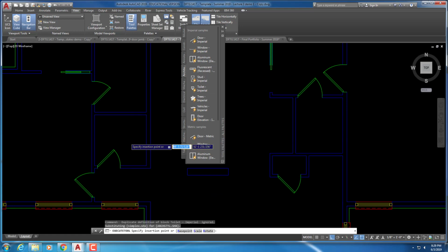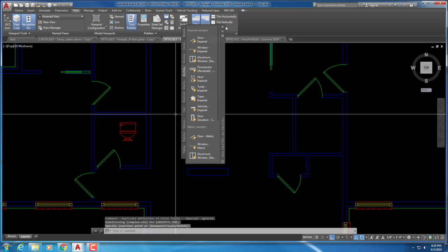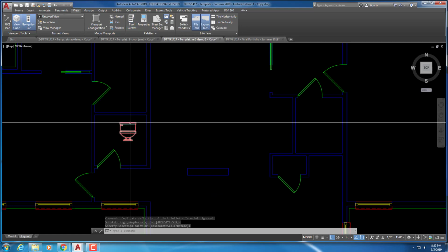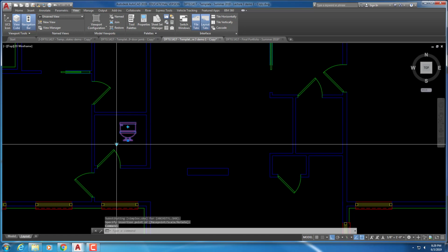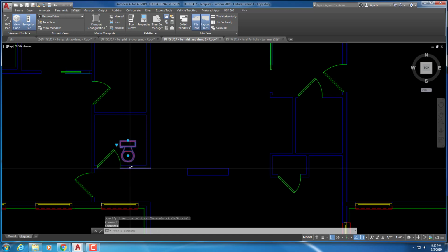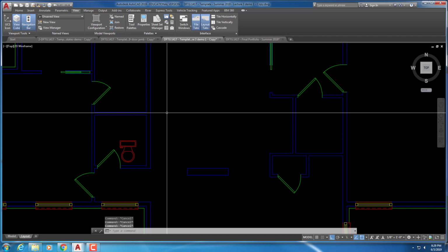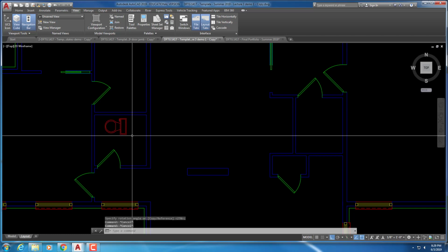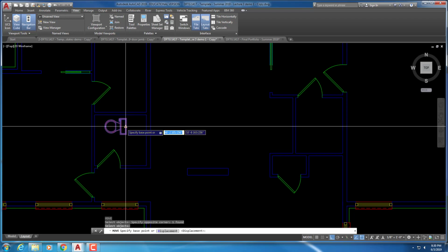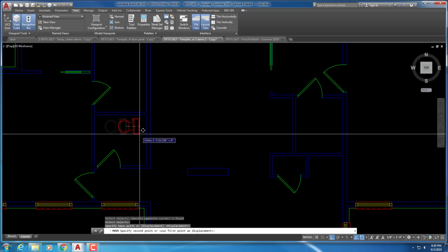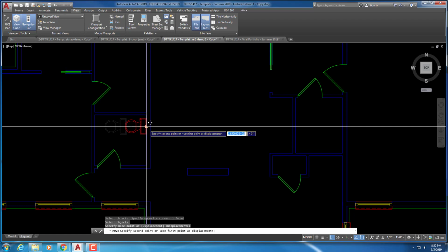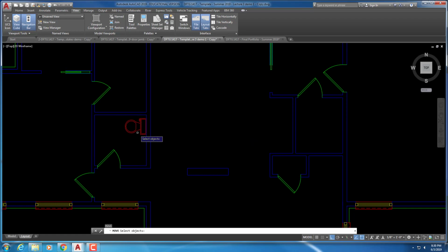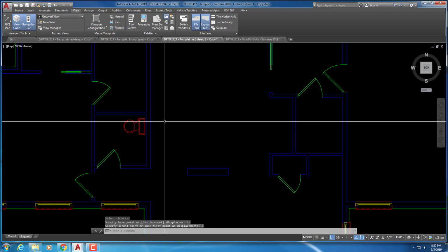It will come in as an elevation, but it is dynamic. You just need to select it and go to here and change it to round plan. And then we're going to rotate that, and they belong 2 inches off the wall. So we're going to move it into better placement next time, but it is going to be 2 inches out from the wall.